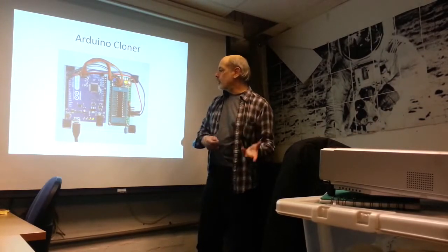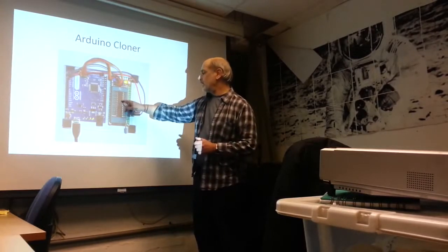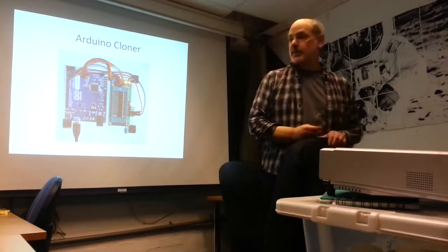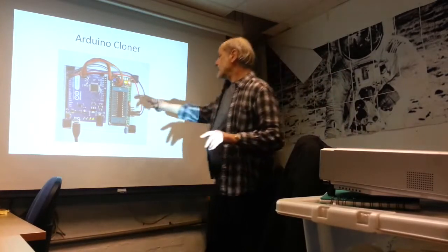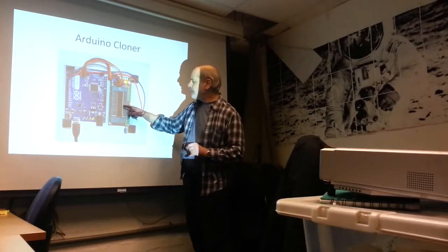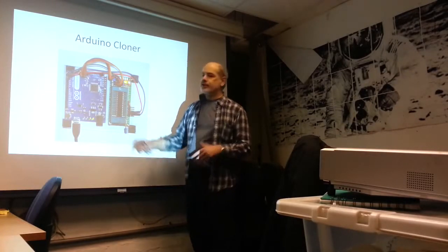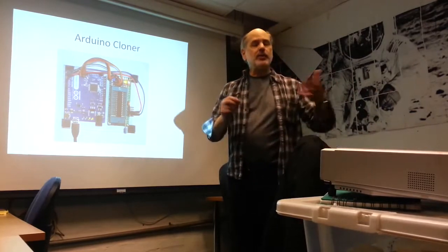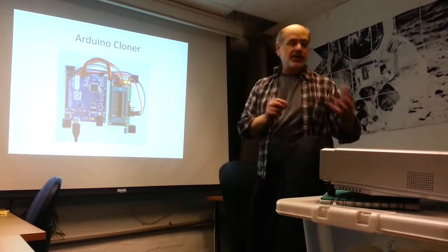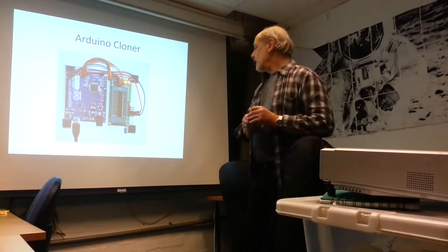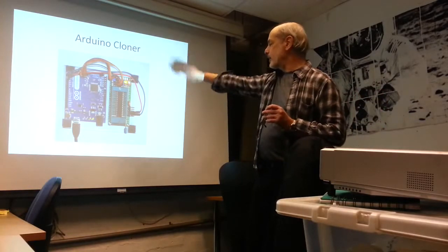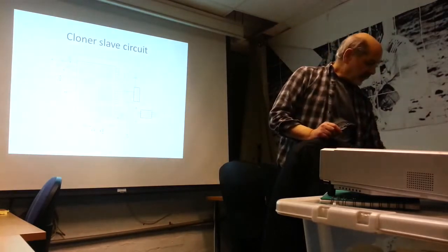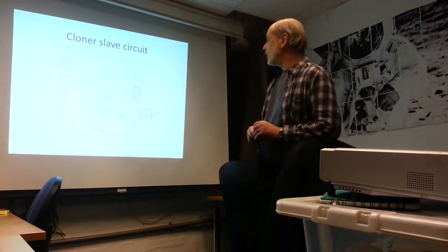And because we're going to be making a number of these Arduino clones for the workshops that we're going to be doing, I've designed some software so that it not only burns the bootloader, but it also automatically uploads the test program. As you know, when you buy an Arduino board, it comes with a test sketch, usually the Blink sketch. So I built some software which both burns the bootloader and loads the test sketch. And I'll give you a link to that later if you want.